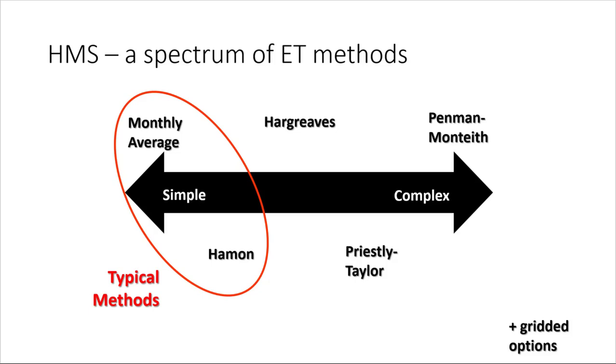Consider the role of ET in your model. If you're most interested in large flood peaks, then spending a lot of time on additional details for ET may not make sense. Most of these methods have gridded counterparts as well, where the input data is specified with grids instead of time series.